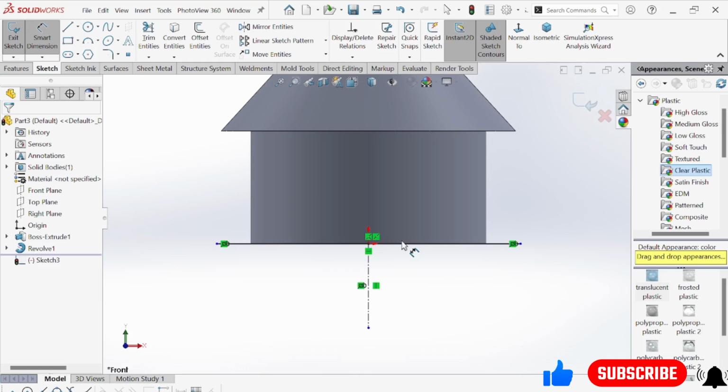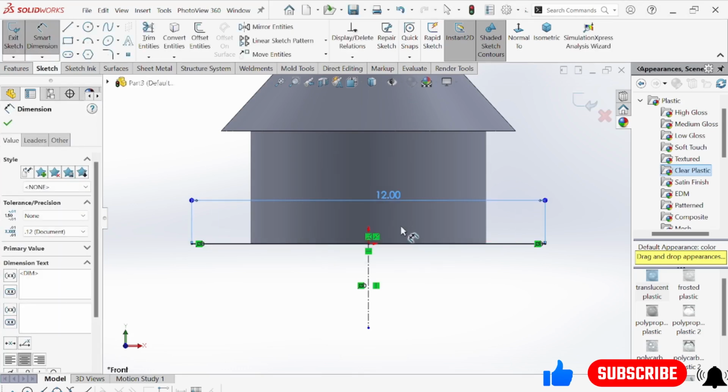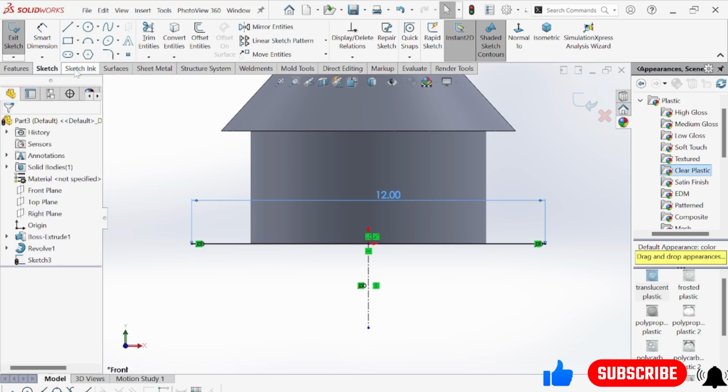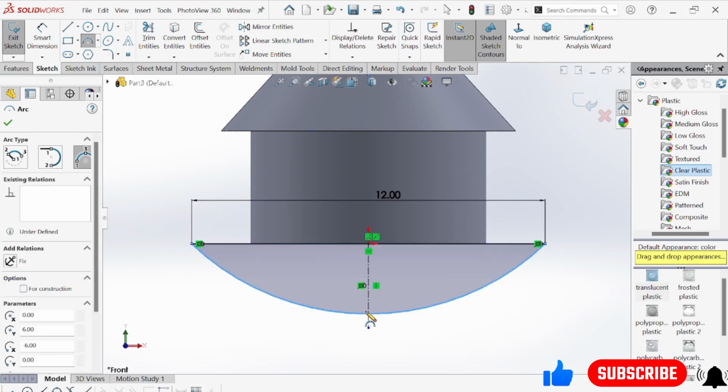Go to smart dimension. Select the dimension. Let's make this one 12 this time. 12 is fine. So select 3-point arc. Here you have 3 options, and you have to select 3-point arc. 3-point arc is more suitable, right? So go here, connect to this point, and make an arc like this.